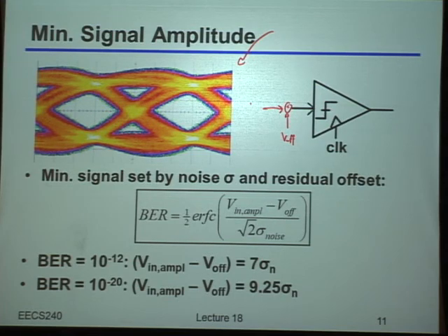Okay, so what we said was that if we had our incoming signal here, we had that offset. Ideally, of course, we wanted to put our threshold right at the center point here. And hopefully it should be clear we want to put it at the center, because if we put it anywhere other than the center, you're going to have less distance in the worst case, either in the upper direction or in the lower direction. Now, if we add that offset in, let's just draw that, for example, in blue. That would, as an example, push us up in this direction like this.